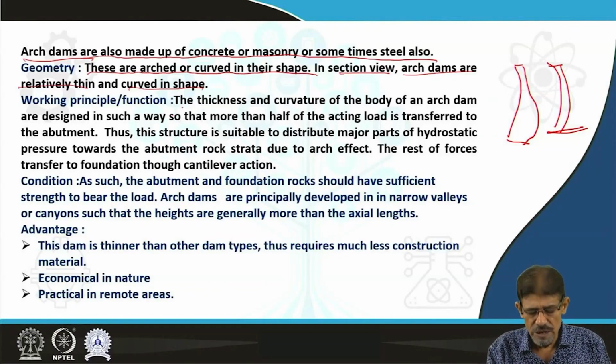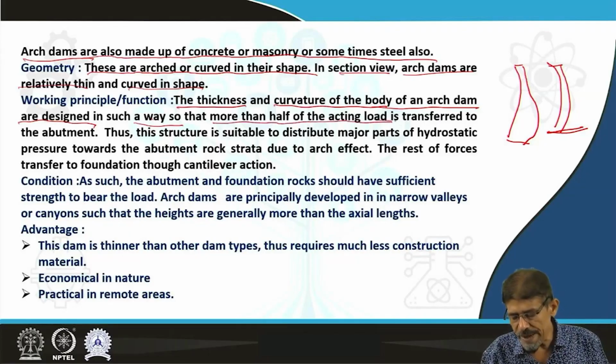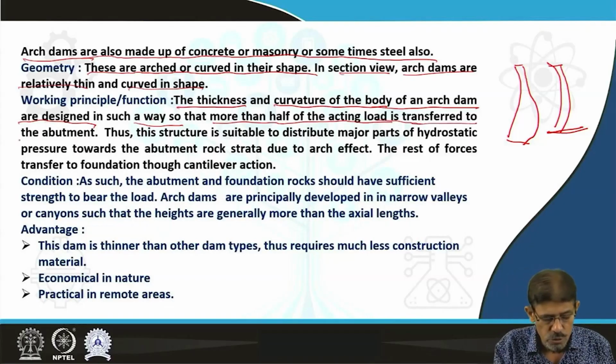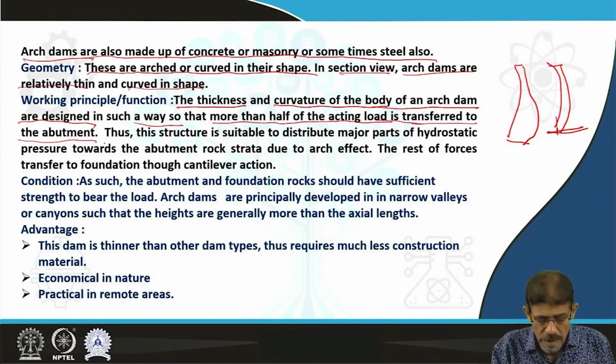The thickness and curvature of the body of an arch dam are designed in such a way that more than half of the acting force or load is transferred to the abutment. The rest of the force is transferred towards the foundation, towards the ground.